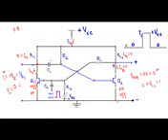See, previously without this input pulse our output was stable, staying at this 0 level. At the instant we apply this triggering pulse, our output voltage will have a transition from 0 to 1 volt. When the transistor Q2 is in off state, a charging current will flow to charge the capacitor C1, and the capacitor will store that charge as a voltage VC1.